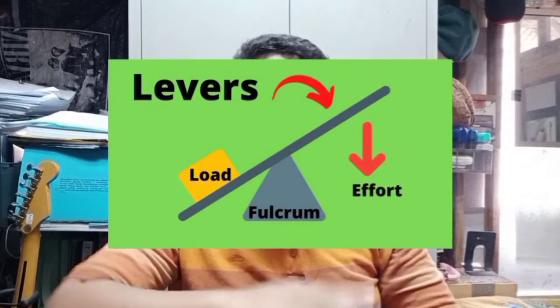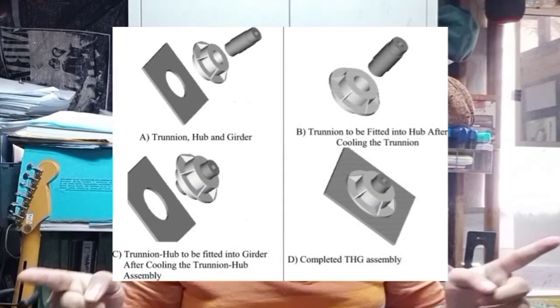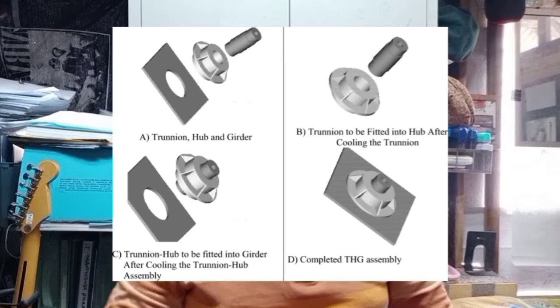So, a bascule bridge is a form of movable bridge which can be raised or closed to allow waterborne traffic such as a ship or yacht to pass. A bascule bridge operates similarly to a lever on a fulcrum. The fulcrum, which is fitted into the bridge girder, is made up of a trunnion and a hub. To make the fulcrum of a bascule bridge, a long hollow steel shaft called the trunnion is shrink fit